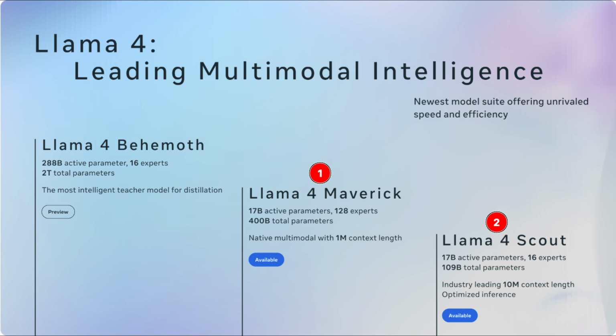It uses special tile registers, so 8 1-kilobyte 2D registers, and a tile matrix multiply, also known as TMUL, accelerator engine, to process matrix data. So it accelerates int8 or BF16 much faster than standard CPU instructions.